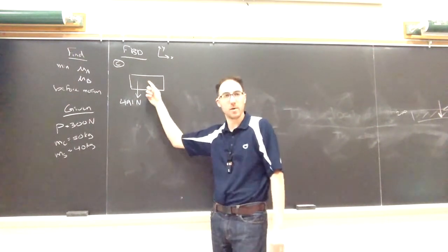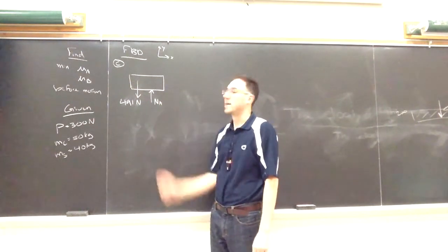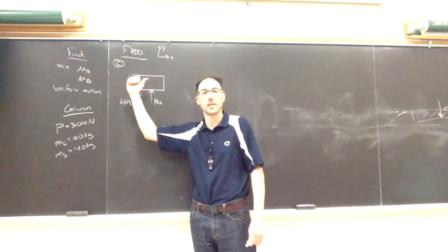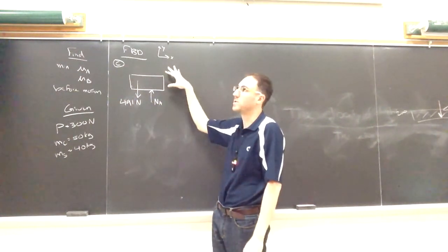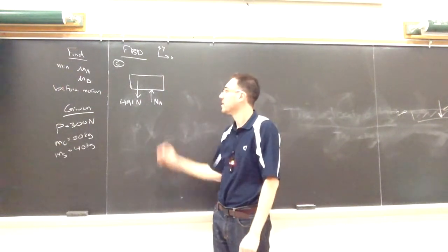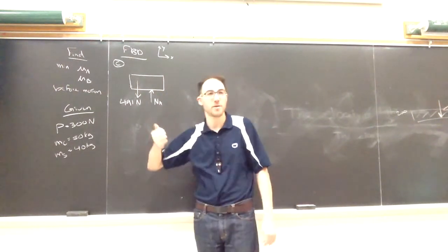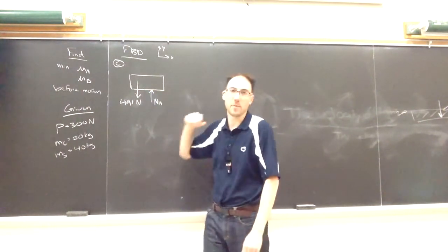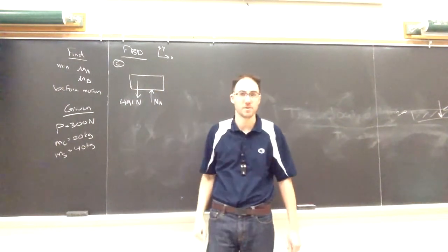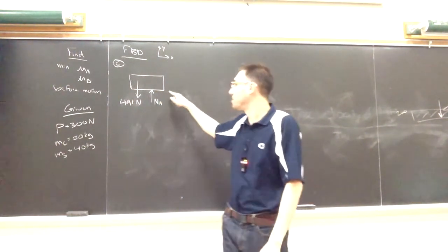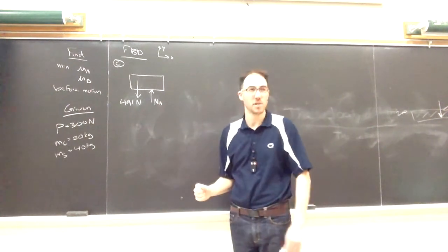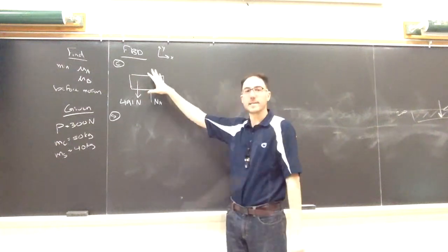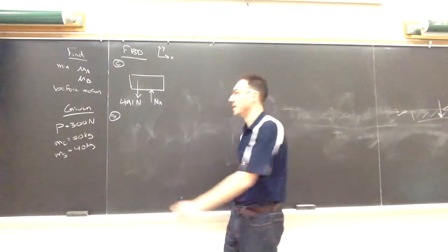I'm going to come back to which wall it's touching, because we would predict that if it's being pushed to the left, then the left wall is in contact. If it's being pushed towards the right, the right wall is in contact. So there'll be another normal force I'll come back to, and what other force is going to act then on block C? There will be friction at this surface that we want to account for, but none on the vertical surface. Again, I'll come back to the direction of it until we think about how the spool is moving, which will maybe make it more obvious what direction the friction should be. This is not done yet. I'm going to circle back to it.